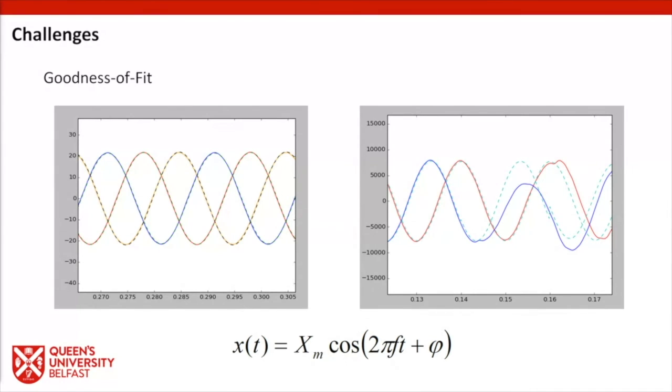We can see here that the dashed blue line, which represents the estimated phasor, doesn't really fit the sampled values that went into the phasor measurement unit. So this is something that I would urge a lot of caution on. There is so much in the way of literature at the moment discussing the use of phasor measurement units to study faults on power systems, both at transmission level and at distribution level. But are phasor measurement units useful for understanding faults? Maybe leading up to the fault, maybe in the aftermath of the fault, but one would argue not necessarily during.